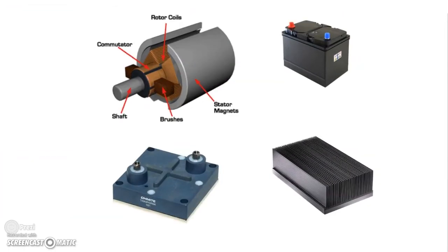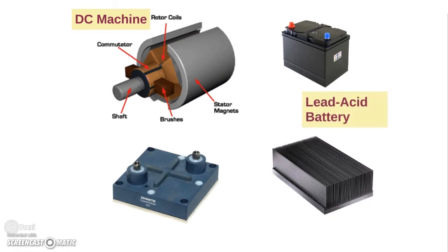A Wells turbine was chosen due to its ability to produce unidirectional mechanical torque in the presence of a bidirectional airflow. The electrical machine was the brushed permanent magnet DC machine, characterized by its machine constant, armature resistance, and inductance. Additionally, a bank of 7 lead-acid batteries, each rated at 12 volts, was chosen as the power source. Furthermore, a resistor bank containing a combination of planar resistors, heat sinks, and cooling fans was implemented as the electrical load.